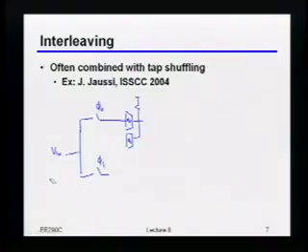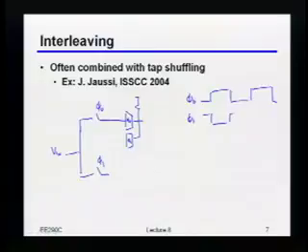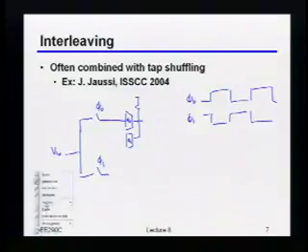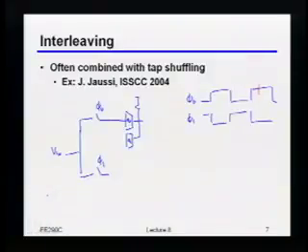Then what that basically implies is that, and I'll maybe draw the clocks here, phi 0 and phi 1. So phi 0 maybe looks like this. Phi 1 maybe looks like that. Okay? So basically, let's say that I was at this point right here. Then that would mean that my first post cursor, or rather, the bit that came before me, was on phi 1. So in other words, if I wanted to build that filter, then I should just take this thing and feed it over here. Does that make sense to people?